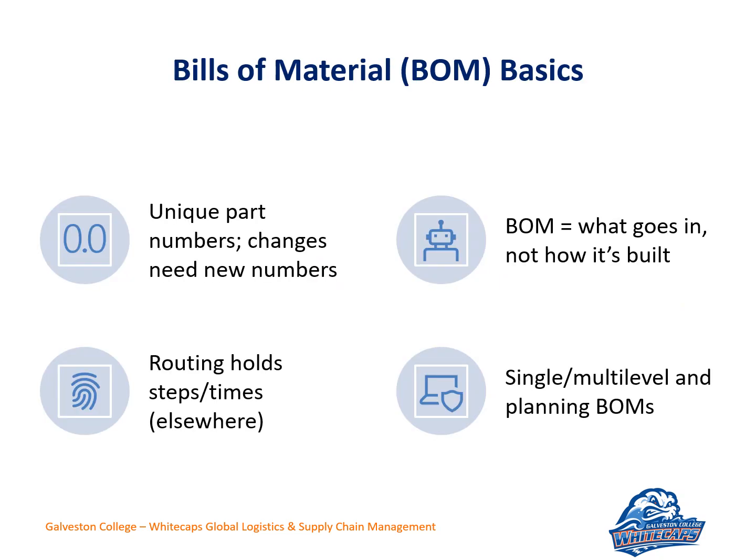So here's an example of some bill of material basics. I kind of covered a bit of it, but it accounts for every item needed to build a product or a parent. You've got to identify all the unique parts, the numbers, any changes, any alternates. Sometimes during a build, there's an adjustment made after the product has been released. You say, am I using the most current bill of materials? Do I have all the products identified on a current bill of materials? So revision is important.